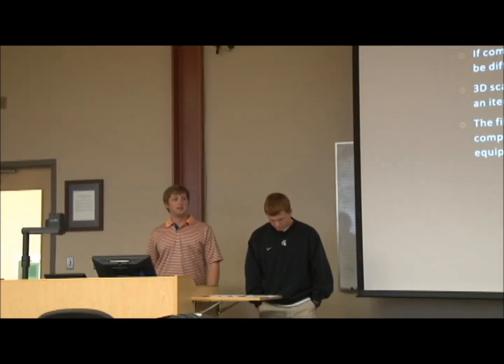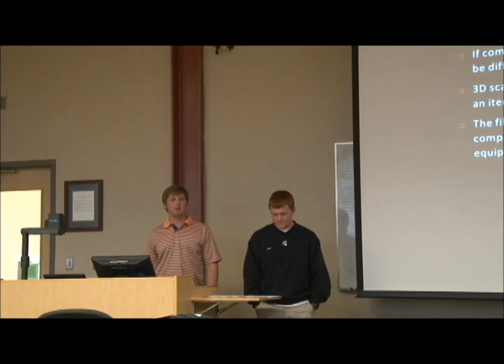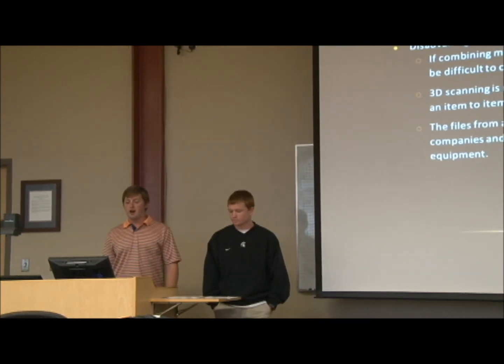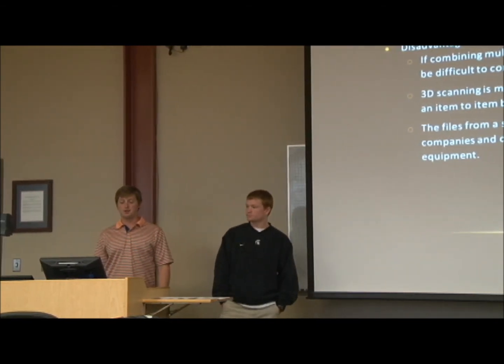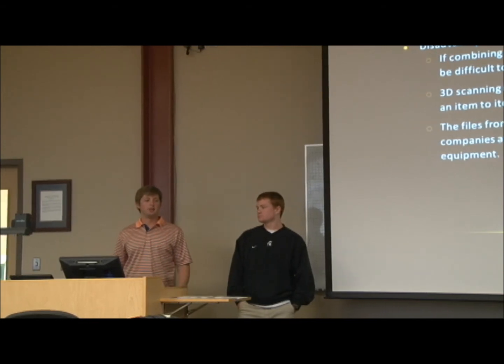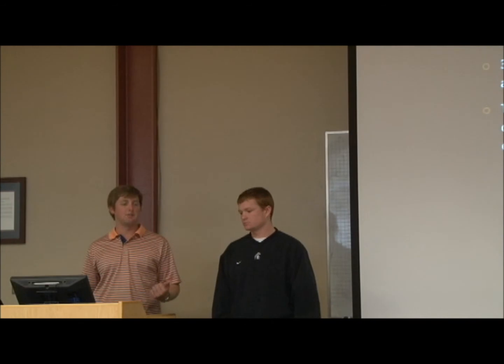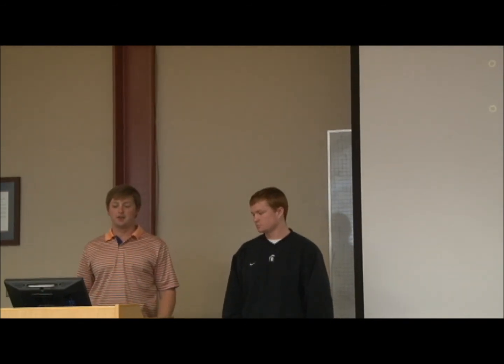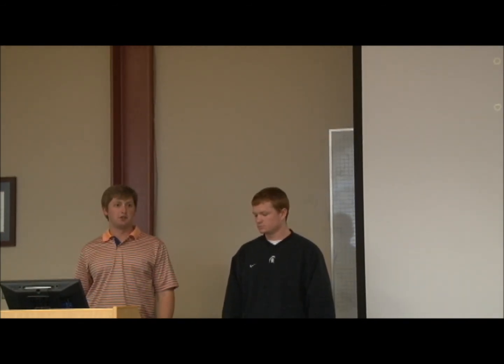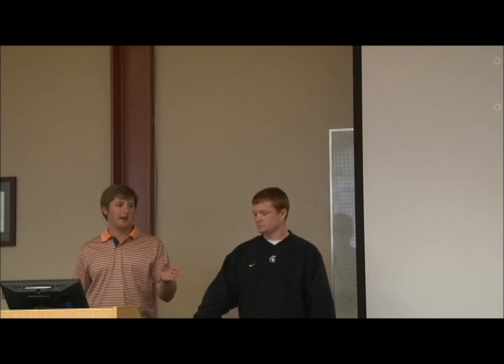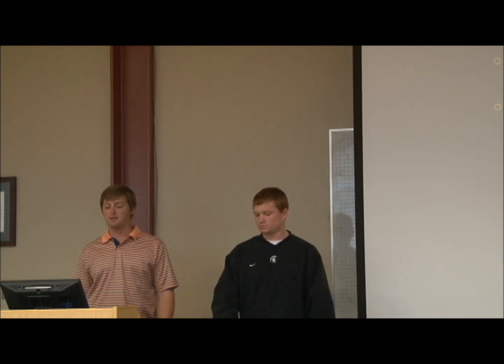A couple of the disadvantages: one scan is called a scan world, and what they do when they're creating a full image is they piece these scans together, and that can be a little bit tedious, and you have to know kind of what you're doing with the software in order to do that. Also, it's more expensive than traditional surveying techniques, but we looked into that a little bit more, and when it comes down to it, between the time saving and all of that, it actually turns out to be cheaper in the end. But if you just look on an item to item basis, it's a little bit more expensive.